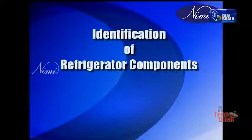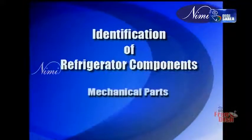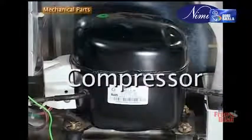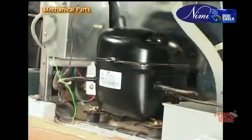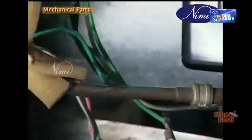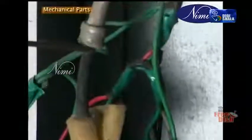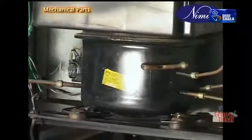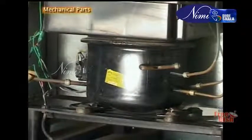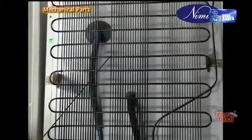Identification of refrigerator components. Mechanical parts. Compressor. The function of the compressor is to provide the necessary pumping action to the refrigerant. It draws cool refrigerant in through the suction line from the evaporator. It compresses it and discharges it into the condenser, where it is liquefied. The compressed gas has risen in temperature and pressure at the time of entering the condenser.